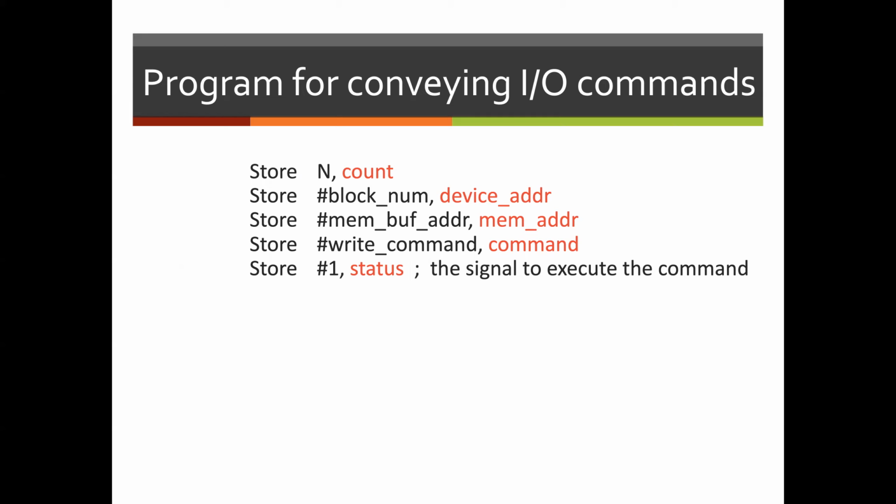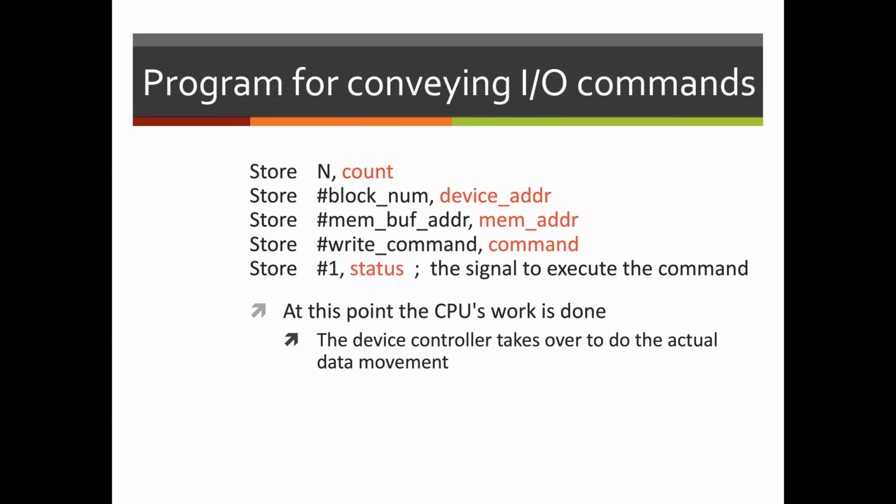We can store our write to the device command into the command register. And then we're able to set our status register as well. It should be noted that these are representative of appropriate memory store instructions. So at this point, the CPU's work is done and the device controller takes over to do the actual data movement.